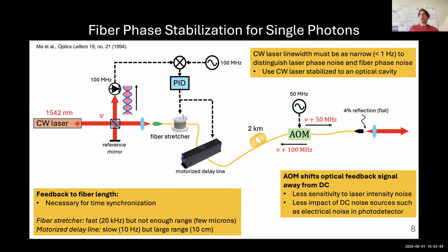That point is probably at a few tens of kilometers, just based on the noise spectrum in the unlocked fiber. Typically fiber doesn't add a lot of noise past a few kilohertz. If it added noise at like a megahertz, then we'd be kind of dead in the water. But you'd break up these links at a few tens of kilometers for very excellent phase stability. If you're willing to make sacrifices in the high frequency phase noise, you can go longer, but not much longer.